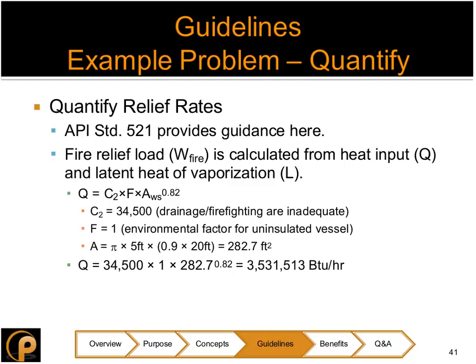Limiting your inlet pressure drop does not always reduce or eliminate your PSV instability. However, that's what's written down, and that's what certain regulatory bodies will look at as a rule that you need to follow in order to prevent unstable operation and in order to fit within recognized and generally accepted good engineering practices. Nobody's going to argue that 3% is bad, but it gets sticky if it's more than 3%.